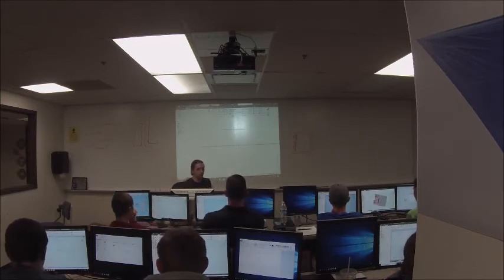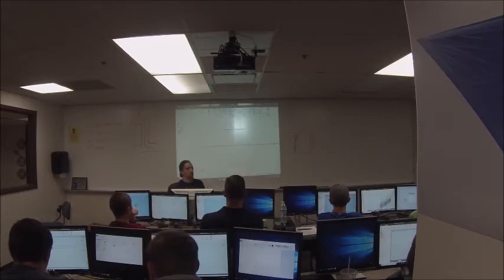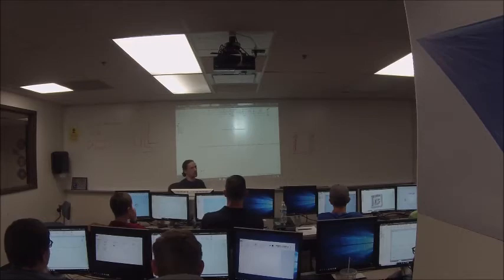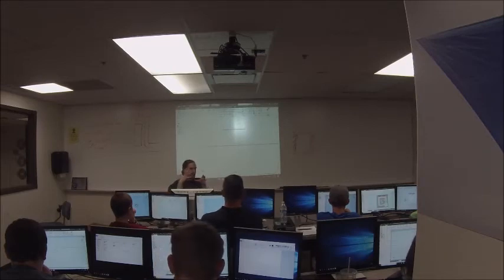Constraints are like logical rules. Inventor keeps track of all the constraints that you apply, and your sketch has to obey all of those constraints. So you're kind of giving it conditions. So you can be any shape you want, except this line always has to be horizontal. Oh, and that line has to be attached to that line. And these two things need to be this far apart, right? You're kind of creating a list of rules, and then Inventor's going to figure out a way to make all that geometry fit, right? Which is why when we're working on a lot more complicated sketches, you'll change a dimension over here, and other stuff in the sketch will change, because Inventor's updating it to fit the set of rules that you've specified for the geometry in that sketch.